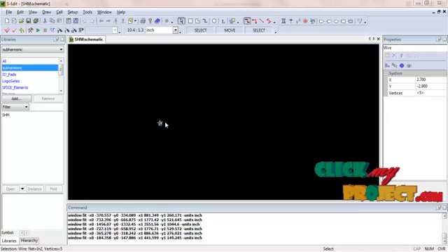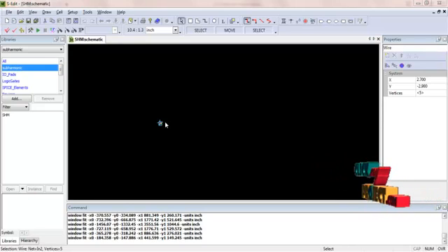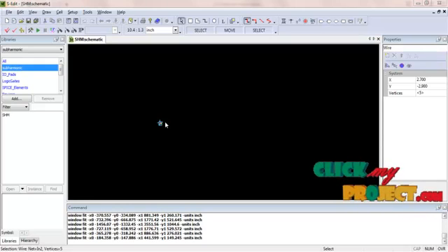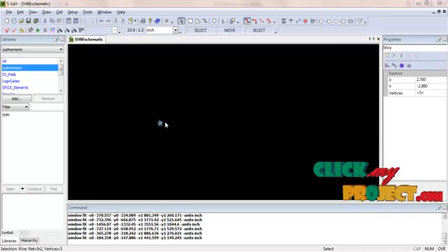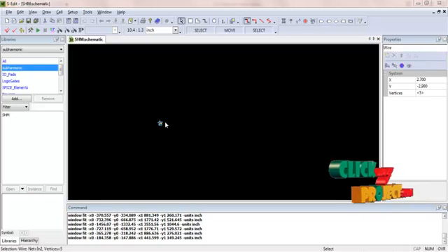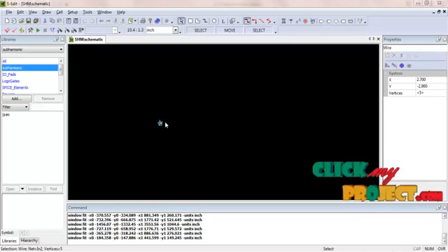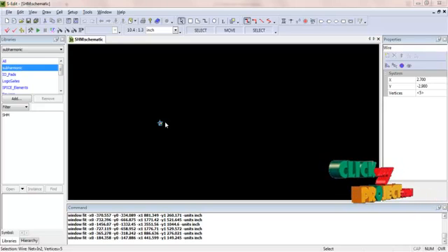For tuning out the parasitic capacitances, an inductor is employed between the RF and LO stages, which utilizes the pi network. The effect of the cancellation circuit on the pi network on the complete mixer is based on the Volterra series analysis in the harmonic input method.